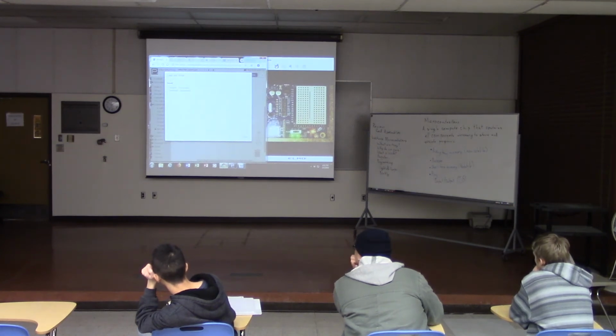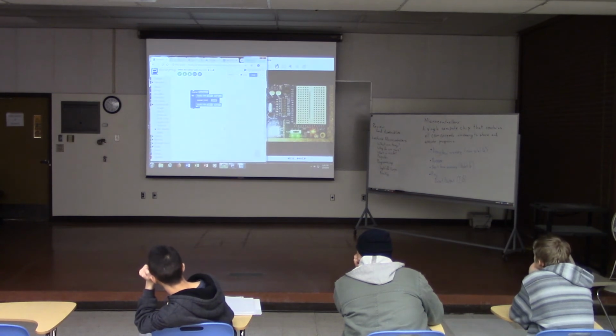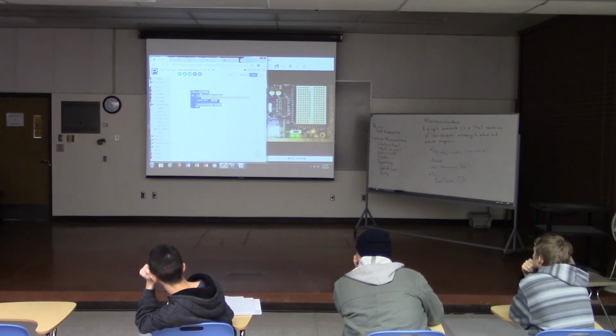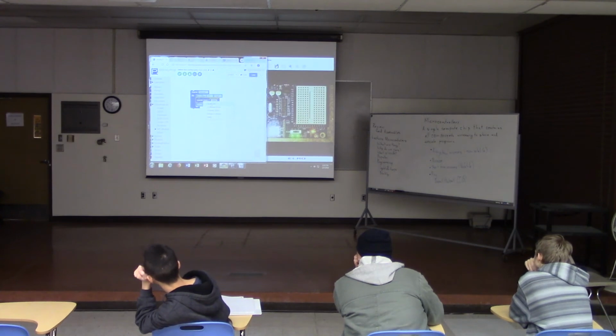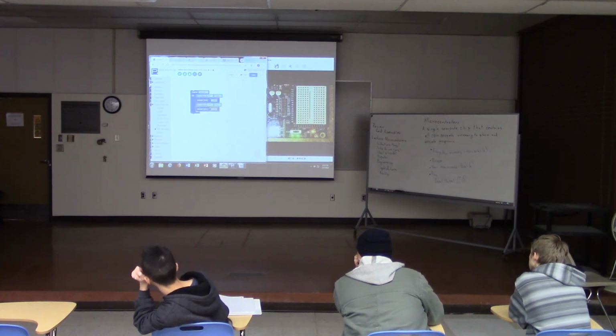It's not blinking like I want it. So what's the matter here? What did I forget? No delay on the off. Yeah, exactly. So I'm turning the pin on, and then I'm waiting, and I'm turning it off, but then it loops back around and it turns it on again as soon as I've turned it off. So it's not off long enough for my eye to actually see. So I need to put another delay in there. So I'll duplicate that, put that down there.